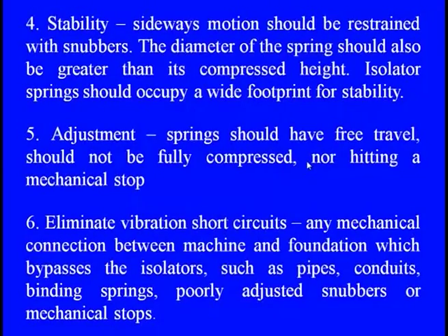Adjustment. The spring should have a free level and should not be fully compressed, or hitting the mechanical stops. It's not that it should be hitting all the time, because of this hitting, impact forces are being generated there.